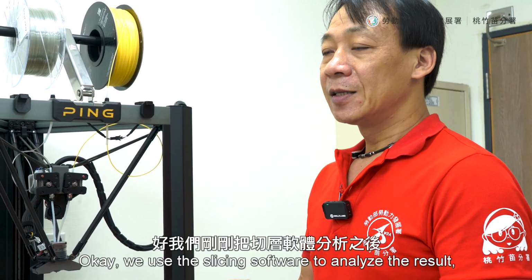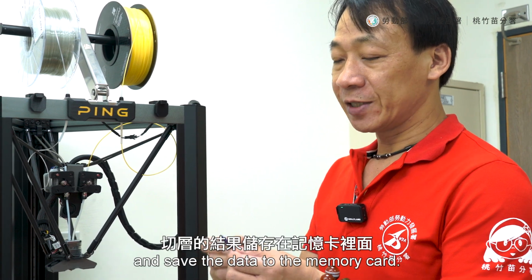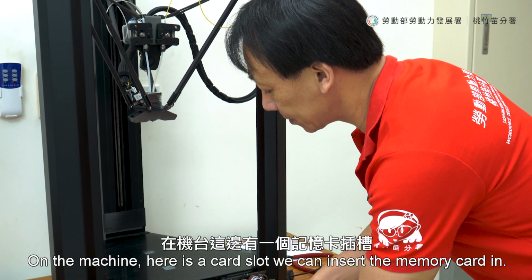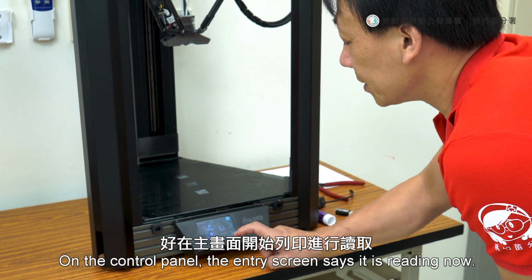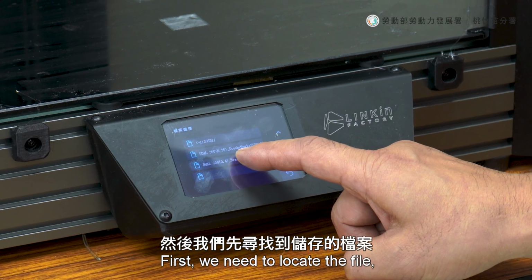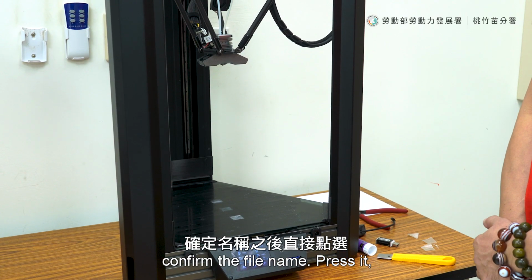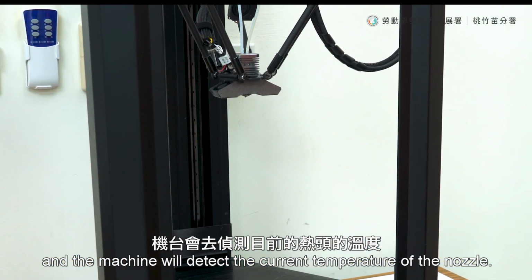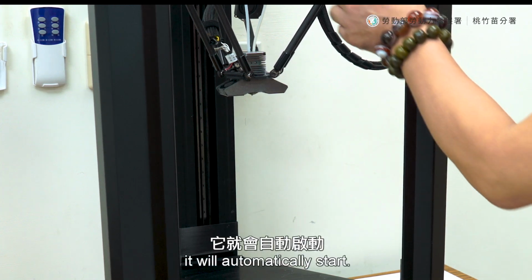Okay, we use the slicing software to analyze the results and save the data to the memory card. On the machine, here is a card slot. We can insert the memory card in. On the control panel, the entry screen says it's ready now. First, we need to locate the file, confirm the file name, press it, and the machine will detect the current temperature of the nozzle. When it has reached the ideal temperature, it will automatically start.